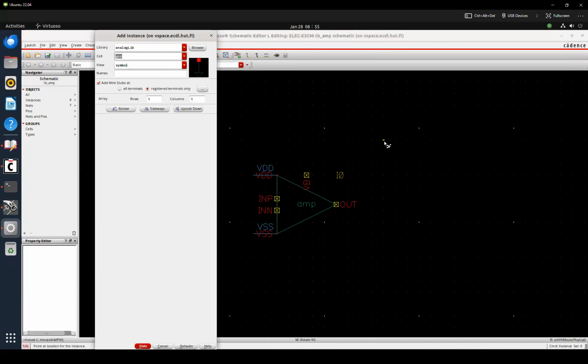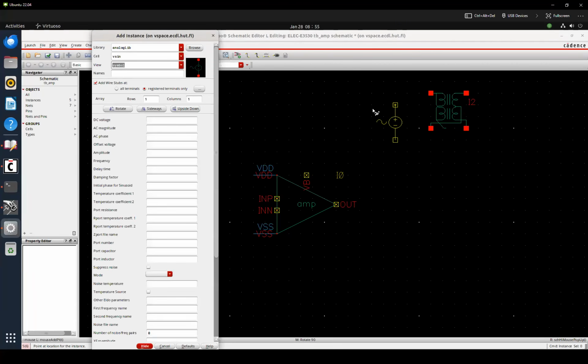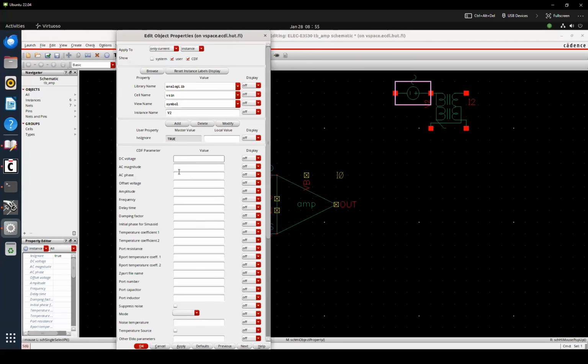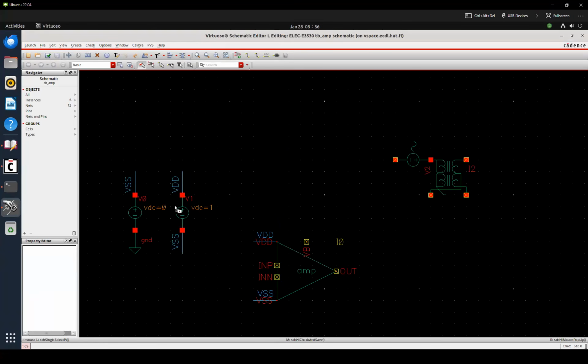And as it was introduced in the document of CAD exercise 2, we can build an ideal balun for the differential circuit simulation. We can put the source here. So AC magnitude we can set as 1. It doesn't mean that we are physically applying 1 volt, but we are applying a unitless voltage that will be helpful for getting AC signals.